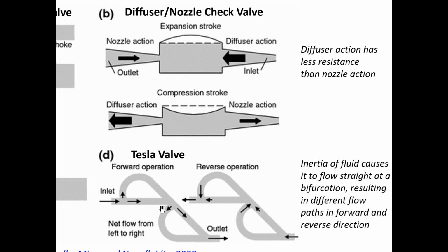So one of the specifications of the pump is how much pressure it can generate, how much back pressure it can handle. If it can't generate enough pressure to push liquid through whatever it's supposed to go through, then you'll end up getting reverse flow. That is referred to as back pressure. So one of the downsides of these types of valve designs is that they don't offer as much pressure. They're not high pressure pumps.